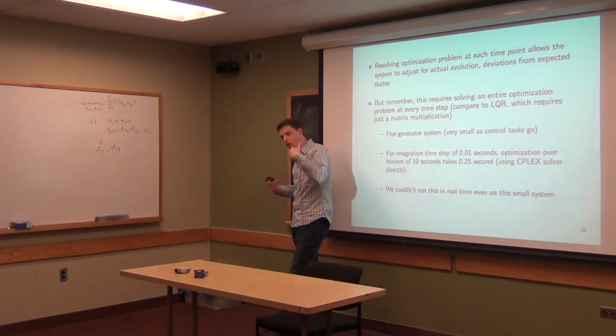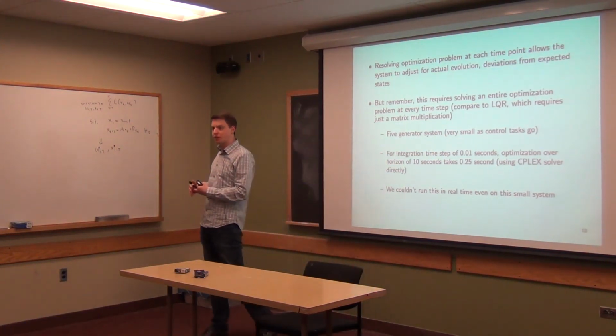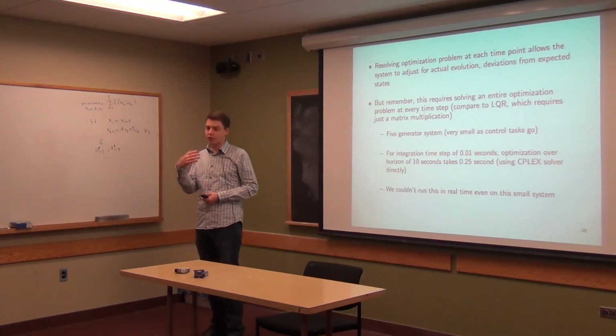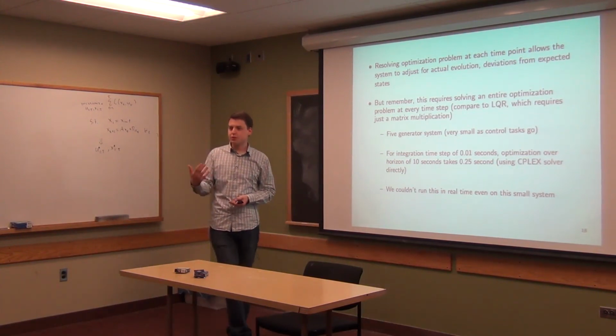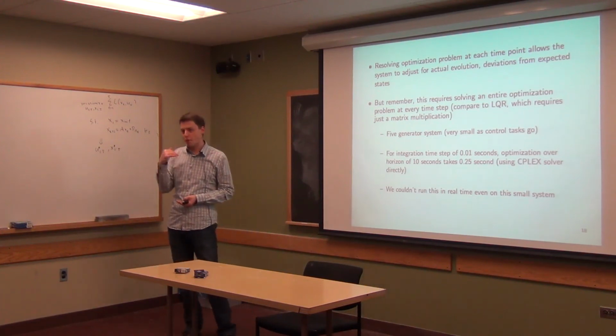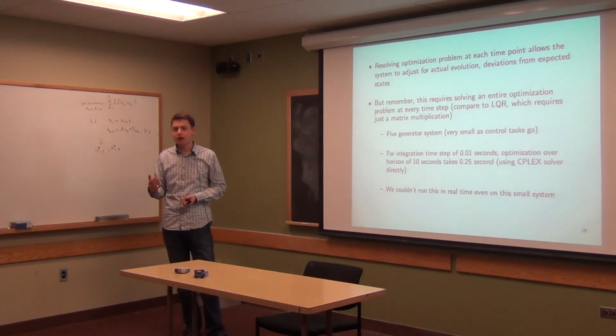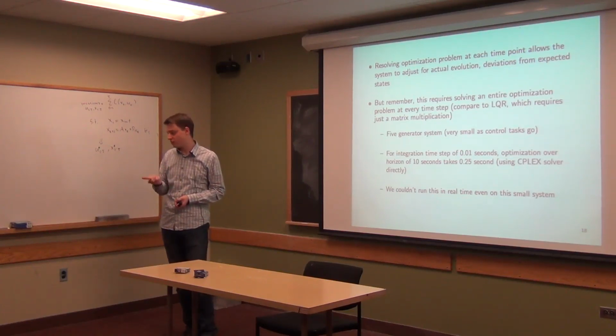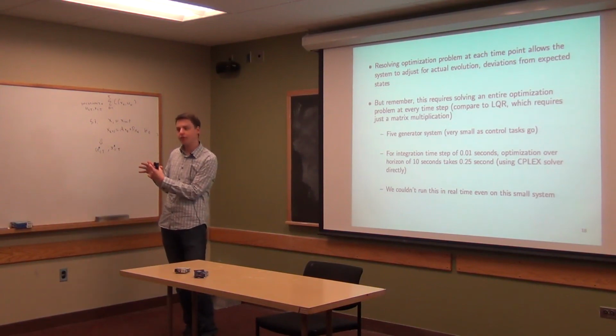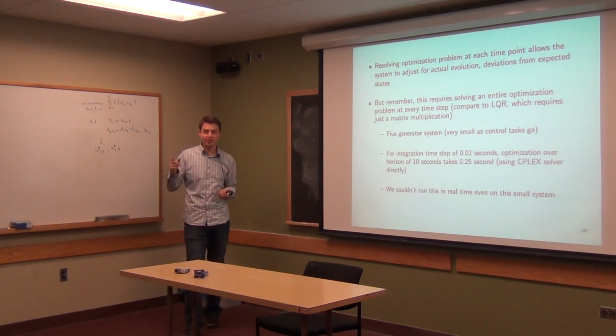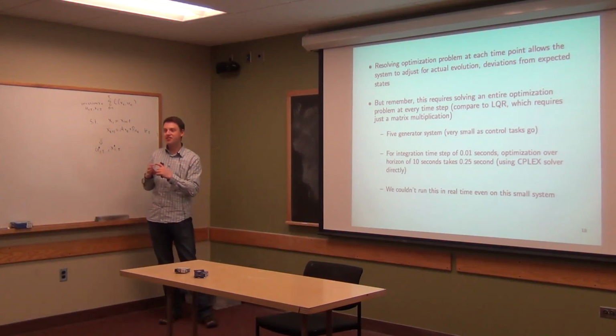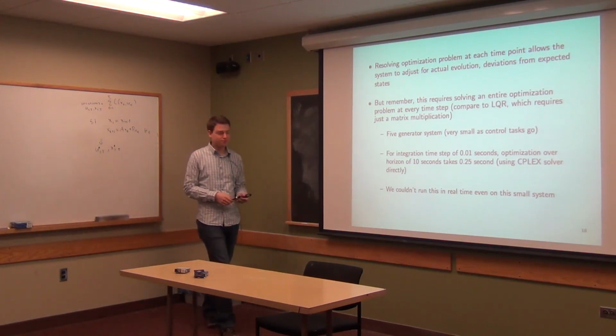So I'm advocating MPC a lot because I think it's very good for a lot of tasks, but it's important to also understand that it does require pretty heavy-duty computation, and that makes it inapplicable for some tasks. Certainly, especially if you want to implement the logic on a little tiny microprocessor, this could be tough to do. Though there is actually work on building MPC engines for little microprocessors as well.